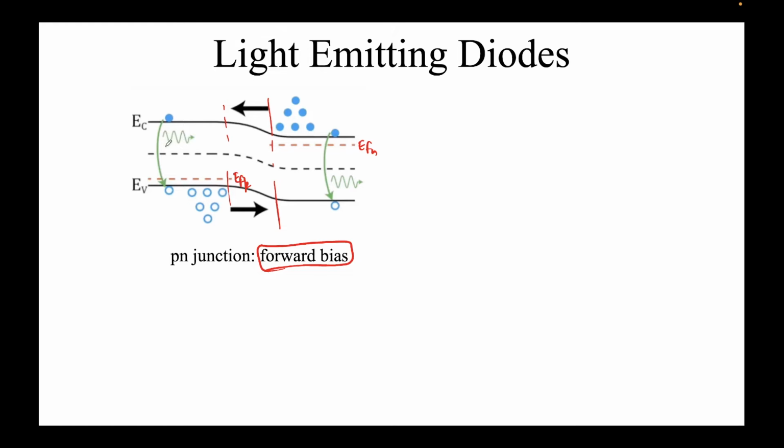You must remember that when the electrons travel to the P side, this is the P side, this is the N side, there is an excess of holes in the quasi-neutral region, and the electrons will simply combine over here. The concentration of electrons drops quite a bit, gradually, exponentially rather, in the quasi-neutral region. We had discussed this in the last session. You can please refer to that or refer to Professor Digbijoy's lectures. So we see the recombination over here. What can also happen is that they can recombine in this region.